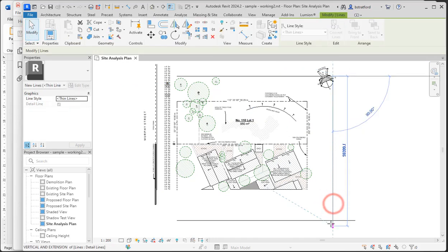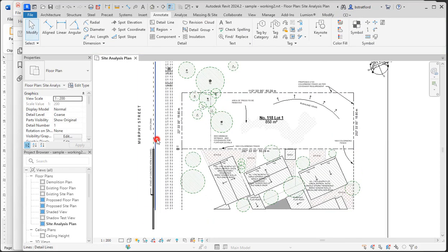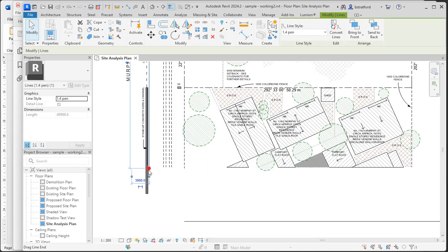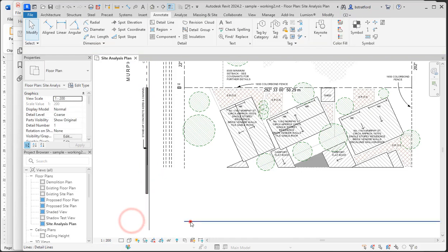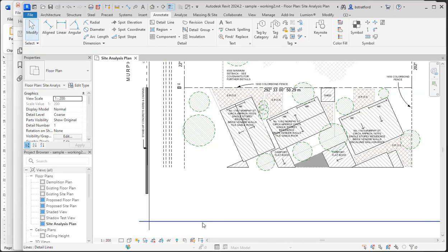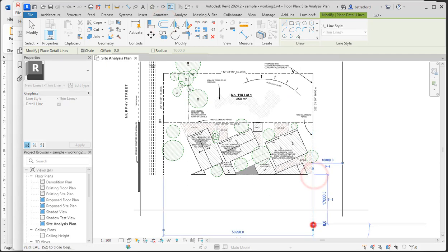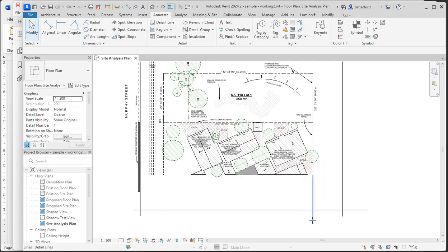I'll drag this line down. The edge of the seal, which is one of the other lines we need, it needs to come down to there. Create some intersecting points between a few lines so that I can pick to place. Detail line, I'll extend this one out. These are all just guidelines that I'll be deleting afterwards once the topographic is in place.